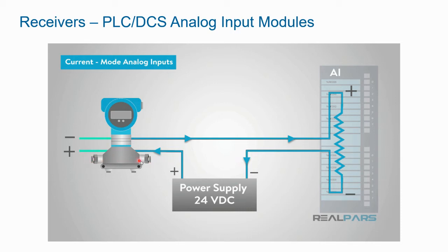Our actual physical stuff is connected through here on this transmitter, and then it gets converted electrically and sent out on the loop. Being that this is a flow, this kind of gives the impression of like a flow transmitter. But anyway, so 4 to 20 milliamps again gets received in the PLC.